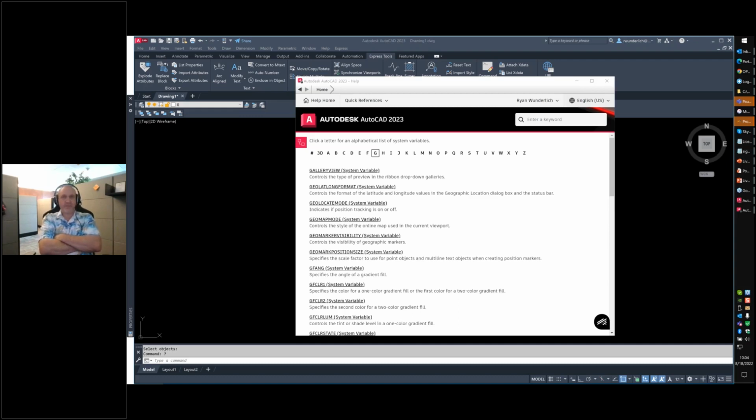Absolutely. Couple of things. AutoCAD Architecture object enabler used to not be built into the AutoCAD core product. It is now actually installed with AutoCAD core. So architecture and MEP drawings should be able to be opened and used by any AutoCAD based product. So Map 3D, Civil 3D without any other issues. Civil 3D is its own animal, Plant 3D is its own animal.